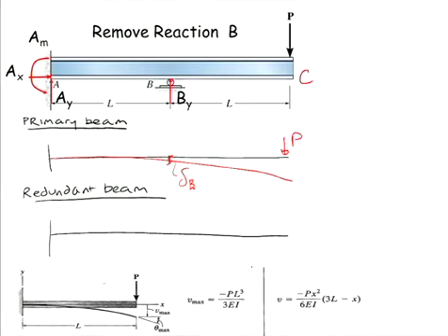So looking at my formula, which one will we use, A or B? It's got to be B, okay? Because we don't want the deflection under the point load. We want the deflection at this point here along the beam. So here, we would say, well, X in our formula here is equal to L, and L in our formula is actually equal to 2L. So these are the variables in the formula.